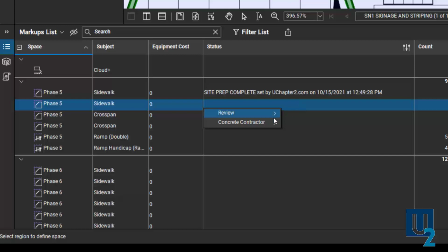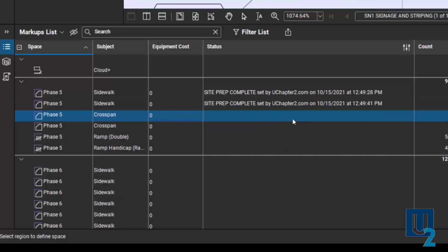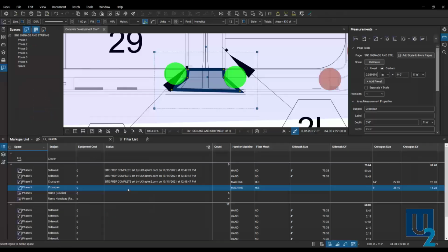So I can come through here and select these different sidewalks that we did all of the site work, and those are all complete. It looks like this one here, the utilities aren't in yet, so the contractor before us isn't ready, so we're going to put that one on hold. I had that turn red so that we know it's on hold.